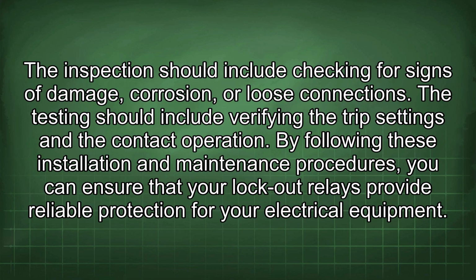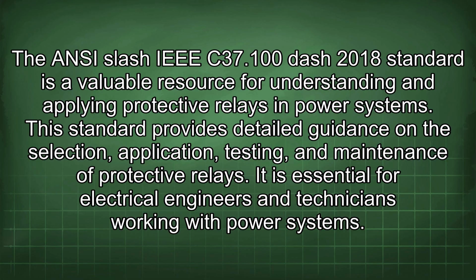The inspection should include checking for signs of damage, corrosion, or loose connections. The testing should include verifying the trip settings and the contact operation. By following these installation and maintenance procedures, you can ensure that your lockout relays provide reliable protection for your electrical equipment.